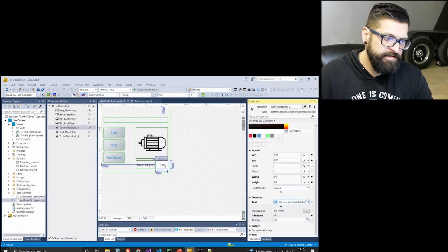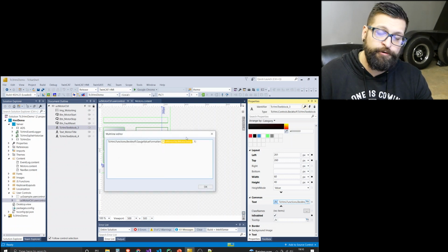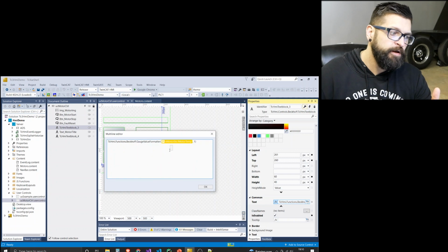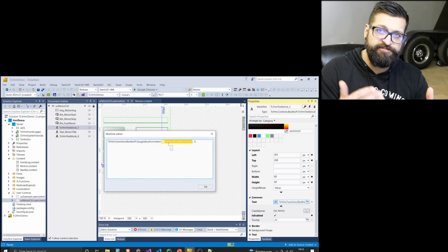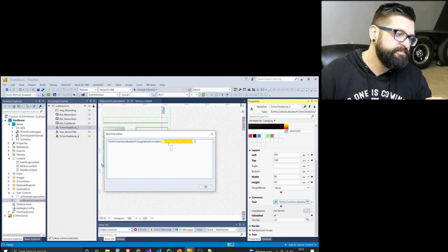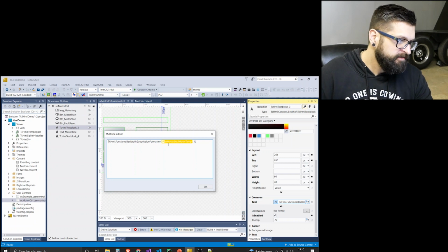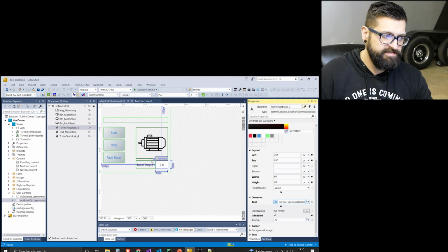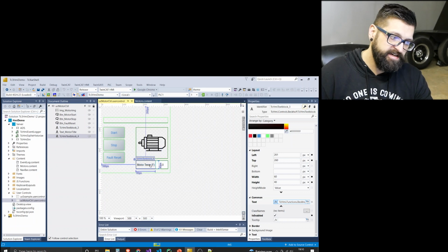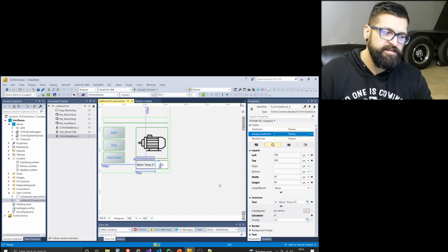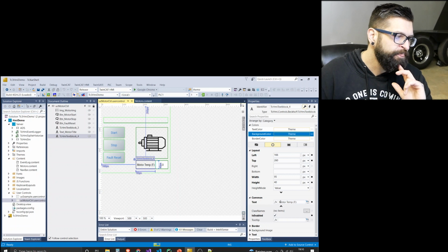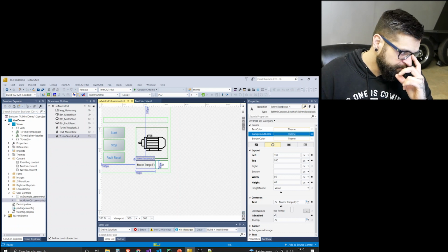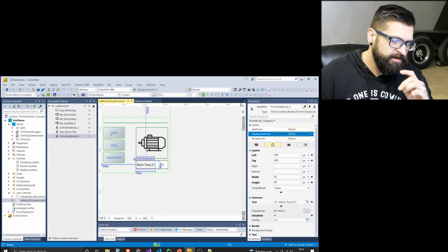And so again, this is indirect because I'm using a parameter. I'm using that motor status parameter that I pass in, one of the elements is a floating motor temperature. So again, this is indirect. This motor temperature, that's just static text because it's just a label. So it's a text block with, down here you can see it's hard-coded motor temperature. And then now let's look at my start and stop, okay?